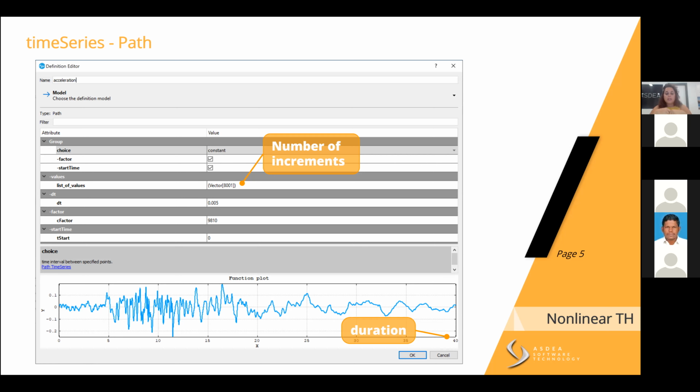So in fact, as a beginning data that you input in your analysis steps, you set the number of increments equal to the number of values that you have in your accelerogram. Or anyway, referencing the dt, you can divide the duration by the interval at which each value has been recorded. This is just a general rule that you can start with, and then you can go lower. So try to have a higher number of increments and a lower dt, so that you can capture an even better response. This is just as a base for you not to miss the response of any of these points.